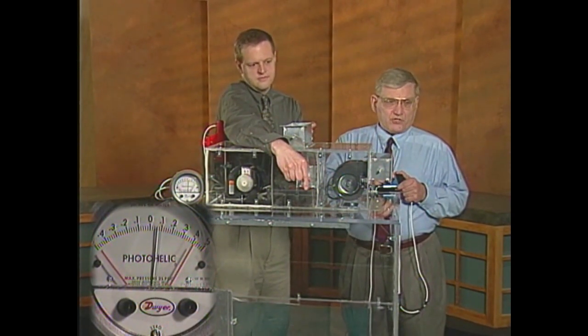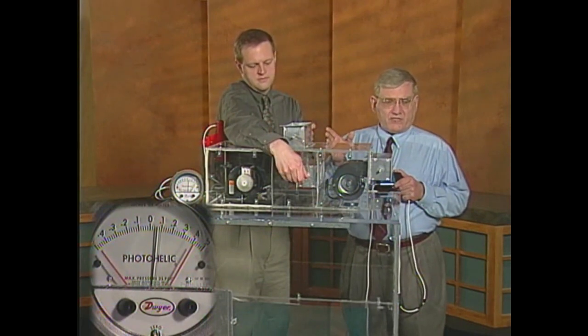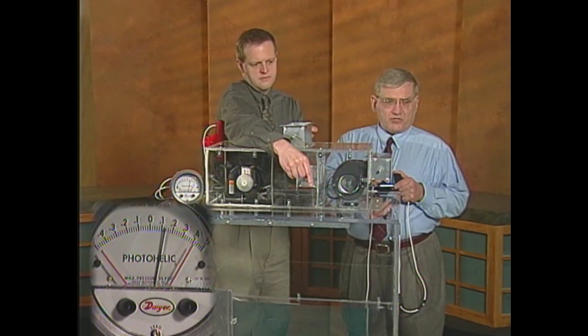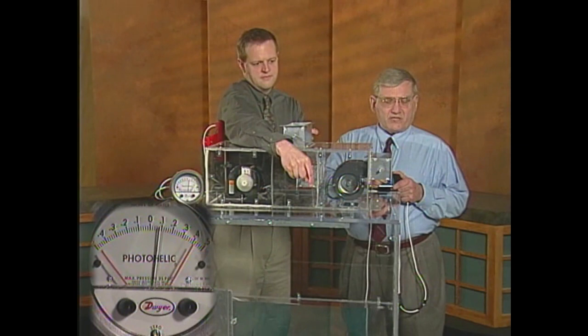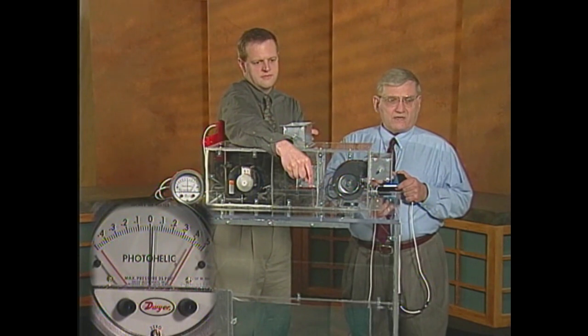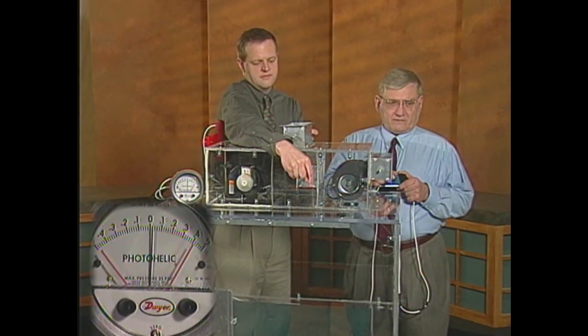Now, as the static pressure starts to build in the space, John's going to increase the outside air. It'll build up the pressure in the space. As the space pressure goes up, I'm going to increase the exhaust rate from the central relief fan, trying to keep the space within a 0 to 0.1 of an inch positive.